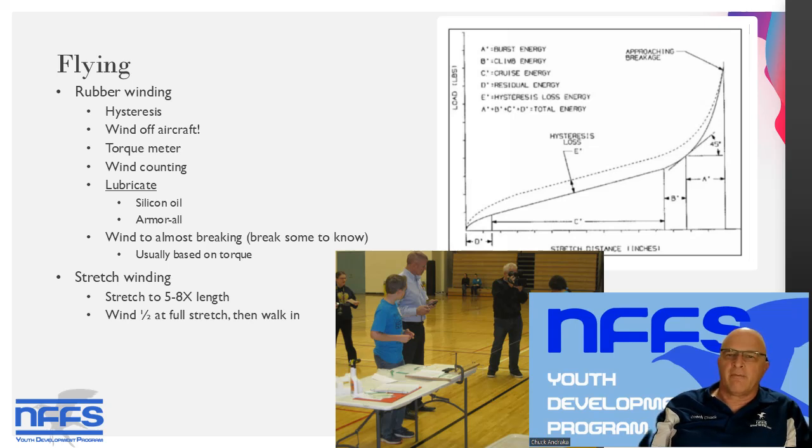So what does this mean? It means if you just wind up to a launch torque, you won't get nearly as many winds as if you wind up to almost the breaking point and then back it down along the unwind curve to your launch torque. You're going to get almost twice as many winds by doing that. So stretch winding is critical. A torque meter is very important. You can get much closer to breaking if you know the torque that's in the motor. You can count your winds, but you're going to get a much more repeatable operation by measuring the torque.